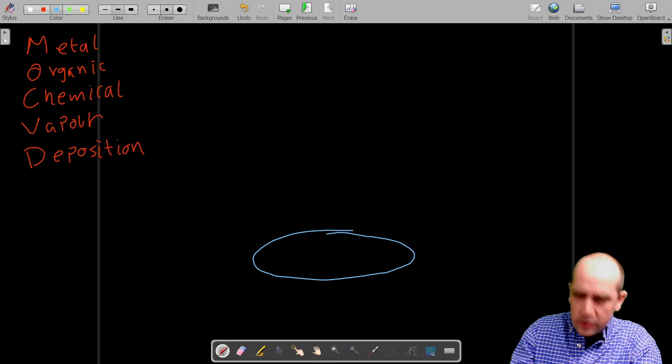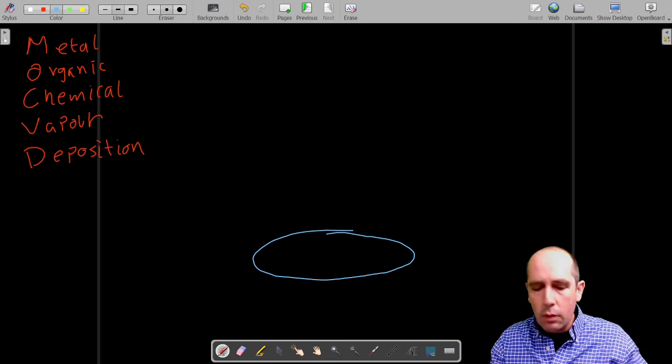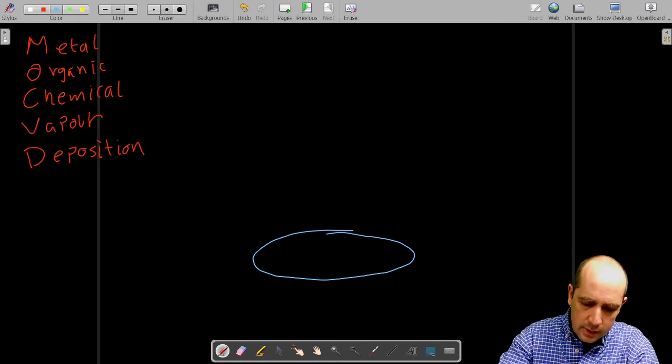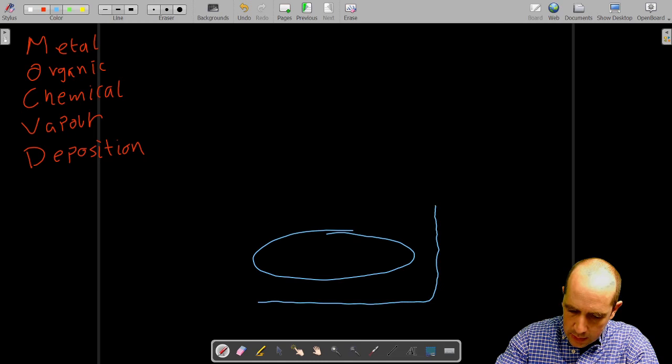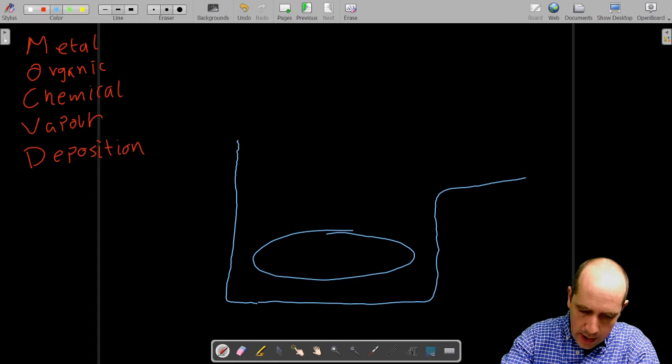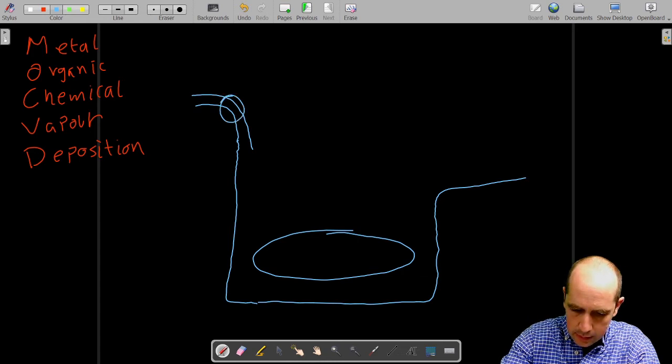So we start with a wafer. So again, a wafer grown with one of the bulk techniques. And this wafer is also put again in a vacuum chamber. But now this vacuum chamber has, for example, the access to pipes that you can control with valves that you can control very well to a few different gases.